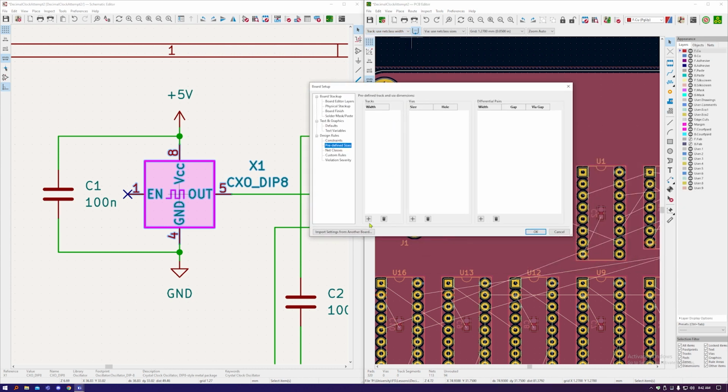And then in the width column, we'll do Add. And we're going to define them in mil, not millimeters, mil, M-I-L. That is a 1/1000th of an inch. It's a bit of an old unit, but it's very common in electronics, and it's used a lot more than millimeters or micrometers for trace widths.